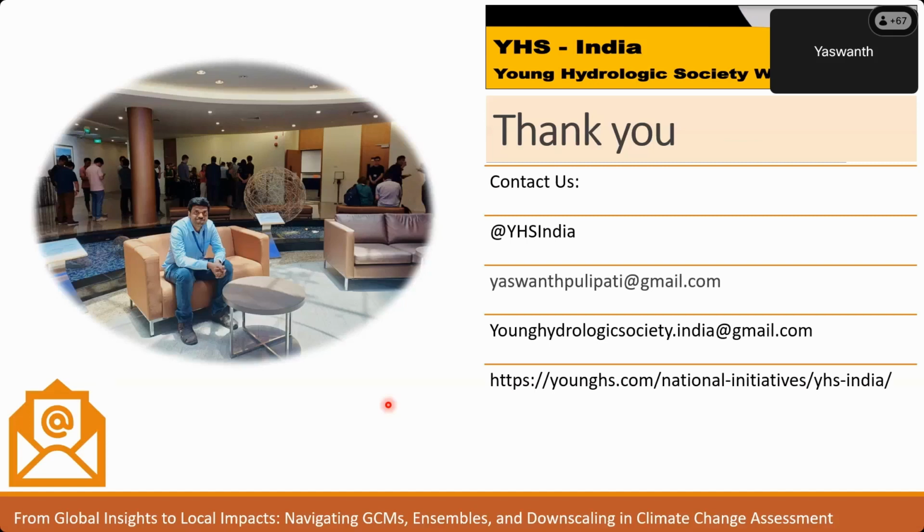There are several gridded data sets available, like rainfall and temperature. But even if you go for 20 years, my suggestion is that you should calibrate and validate. If you calibrate for 20 years, you don't have a validation period. So I would suggest not going with 20 years, but choosing the available gridded data sets and doing the corrections. Even if you say the data is scarce, you can just do the calibration and check if it matches well, and then go ahead. But this is not a reliable suggestion.